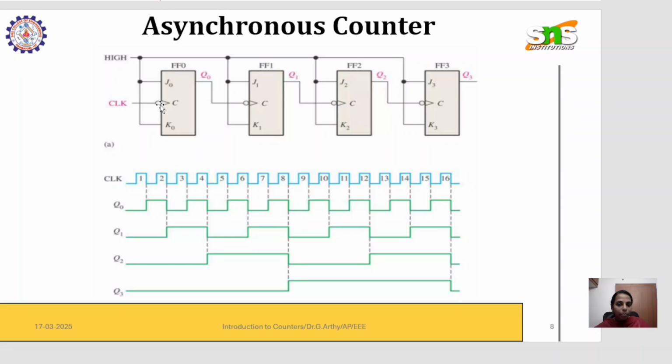Here the bubble with an arrow shows that the clocks are edge triggered, and the bubble indicates a negative edge triggered clock. When there is a negative edge, that is, a transition from 1 to 0 in a clock, we call it a negative edge triggered clock. During the negative edge, or trailing edge, the tasks are initiated.